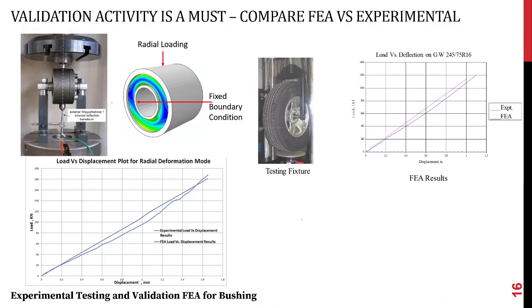And finally, setelah buat apa-apa analysis pun is much better, and you will get better confidence kalau kita buat eksperimen lah. For example, this is the bushing, the rubber bushing inside. Kita apply load and then kita dapat result dia sama sebiji macam eksperimen lah. FEA dapat straight line, perfect ideal condition kan. FEA yang warna biru ni. Oh no, purple. And then in real life, the correlation is maybe about 5% different. So this correlates very well.